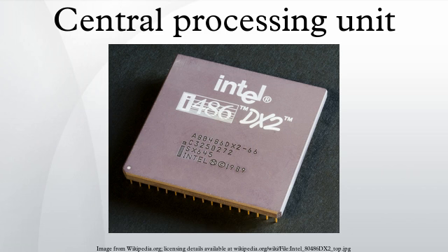The great utility in creating CPUs that deal with vectors of data lies in optimizing tasks that tend to require the same operation to be performed on a large set of data. Some classic examples of these types of tasks are multimedia applications, as well as many types of scientific and engineering tasks. Whereas a scalar CPU must complete the entire process of fetching, decoding, and executing each instruction and value in a set of data, a vector CPU can perform a single operation on a comparatively large set of data with one instruction. Of course, this is only possible when the application tends to require many steps which apply one operation to a large set of data.